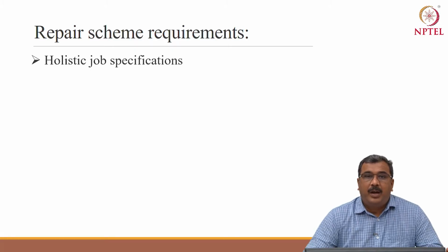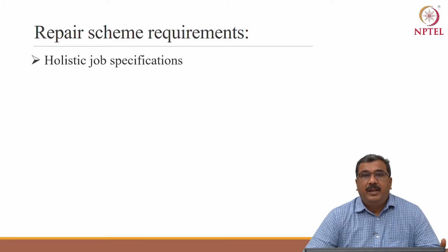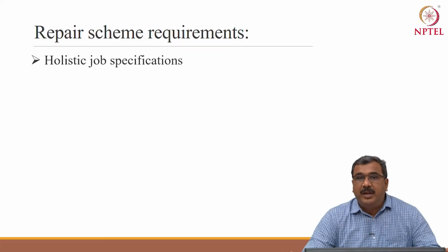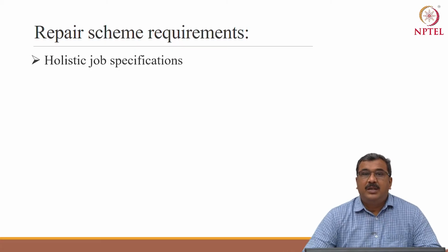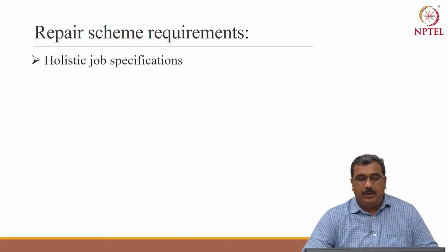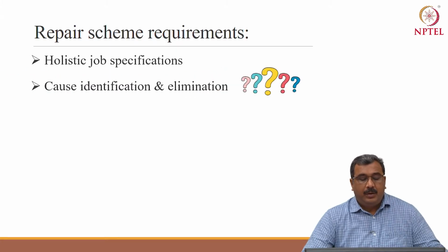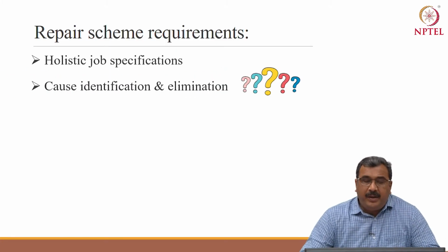You can have a carbon fiber strengthening, but then you need a final finish with a protective coating, or you may need further beam strengthening by using steel plate. You need to check whether these both will comply or not. You must identify the cause.